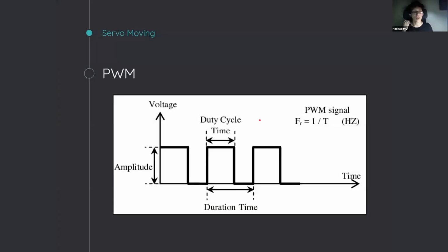So they are controlled with something called PWM, which is a kind of signal that you can get from microcontrollers and single board computers. Right now the Raspberry Pi, as I'm aware, doesn't have a pin that has a PWM from the controller. The Arduino has it. Most Arduinos have a PWM output. If not, you can create it, which we're going to do here in this part.